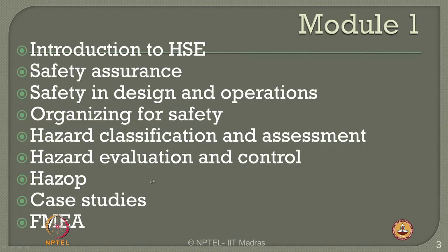We also told you and assisted you on how to prepare a risk priority number, which is helpful in assessing risk in an envisaged new kind of problem, and can also be helpful in ranking risk quantitatively in a given system. So, we helped you through some case studies on how FMEA can be computed. We also showed you how FMEA can be done for a newly developed design platform like the offshore Triceratops, from stage by stage till experimental evaluation.